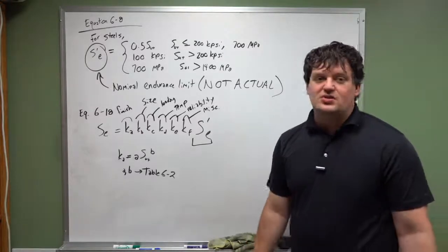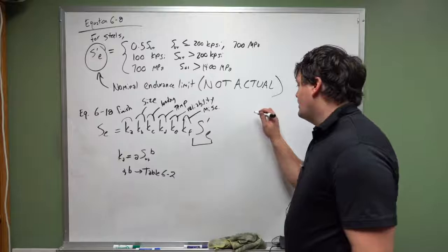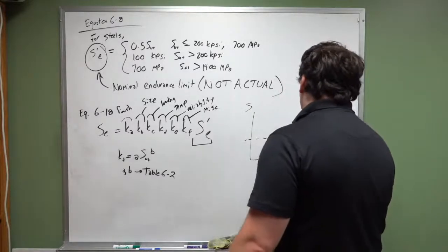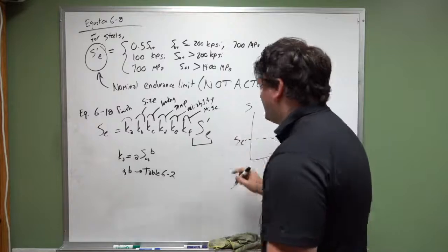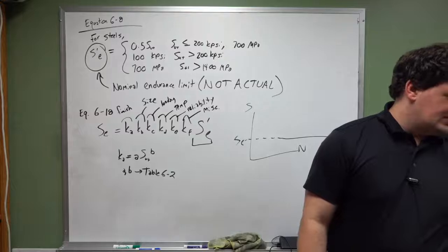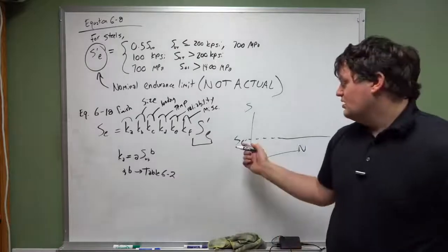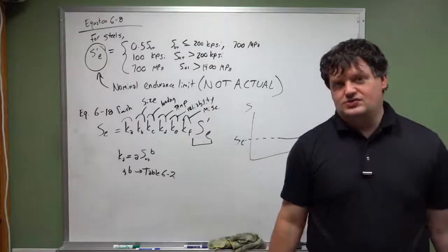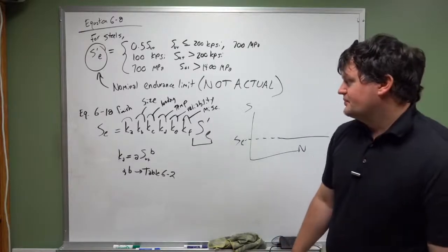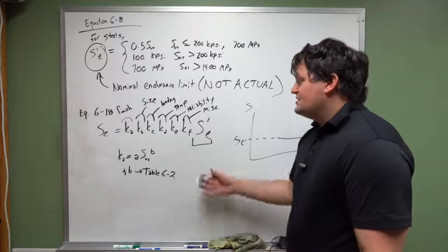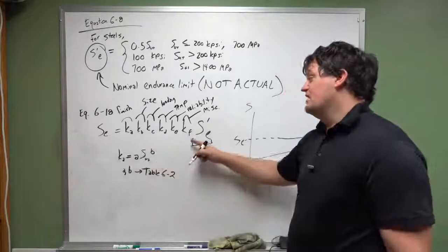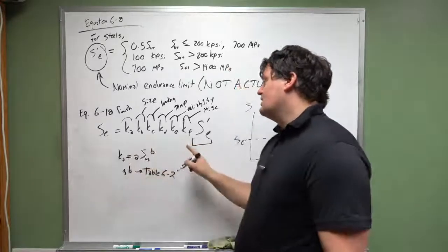And this endurance limit ultimately states, on the SN curve, this endurance limit is that infinite lifespan. So this is really pertaining to items that have a lifespan greater than 1,000 cycles, 10,000 cycles, 100,000 cycles. Okay. So this is the endurance limit, and you can use the formulas and the tables to find each of these variables and plug them in here.